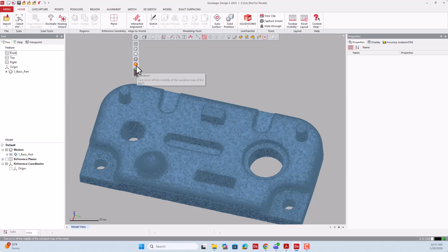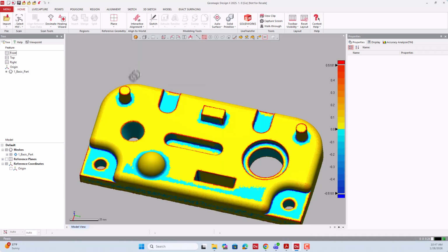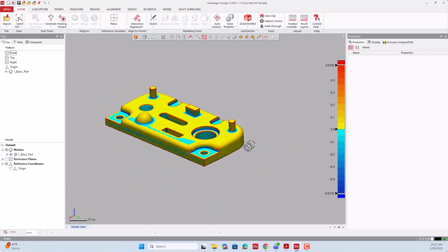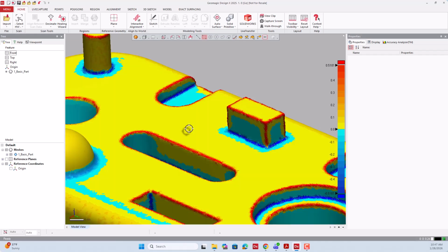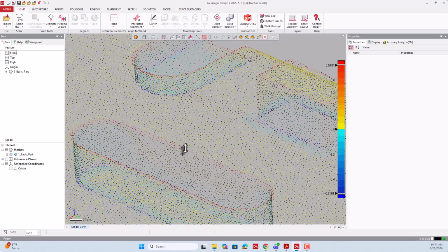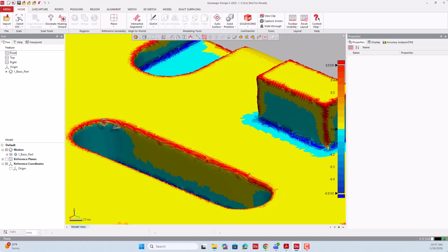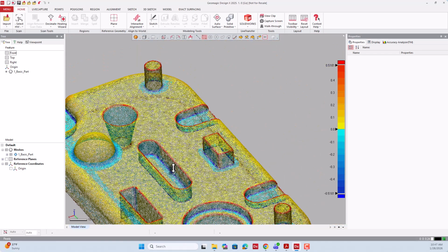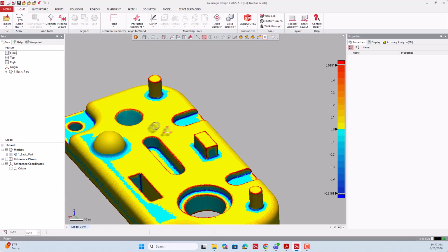And after that, you have something called curvature. So if you click on curvature, the software will by default plot the curvature of this mesh. You can zoom here and see that there are a lot of colored zones. You see that this convex area is shaded in red because there's a higher variation in curvature, and that area is filleted. That's why it's showing in a deep red. This concave area is shown in a blue color. This fillet is inverse, so it's shown in a deep blue color. And the gradually varying areas have more of a yellow coloration.